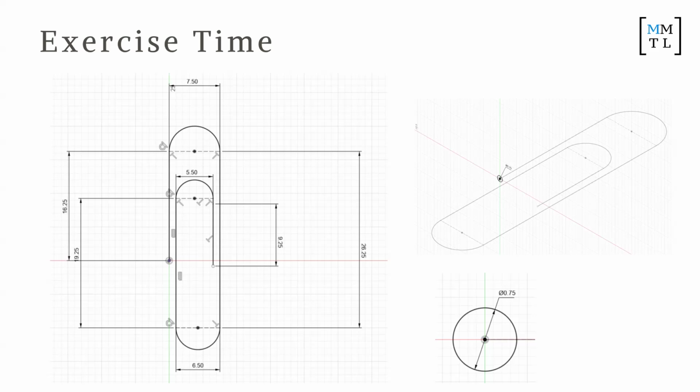I'd like to try sweep it. And now go to sketch. The profile is like a circle, but it has to be on the front, so I recommend going to up here. That's good. So which side is the... Okay, that's fine. You can try to change the distance, do you see what happens? It's between 0 and 1, because 1 means the whole path. So it's just the percentage of the path, not millimeters or anything. So that's like 75. And then I finish sketch.